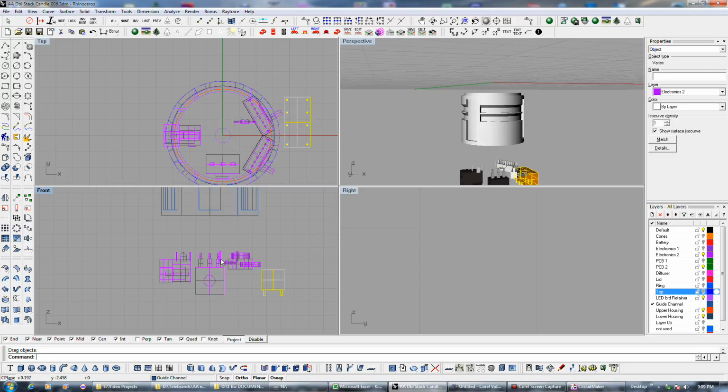All these components, by the way, are upside down, including the resistor, because if I mount things like this, again, it's a single-sided board we're going to make, so it's going to be full side up, so solder joints are going to be on this side. So at any rate, if I put the relay in here somewhere, it would have to be upside down from its current position, but I'd have to put it in here somewhere well below our components. It'd have to be at least that deep, but that would work, though.